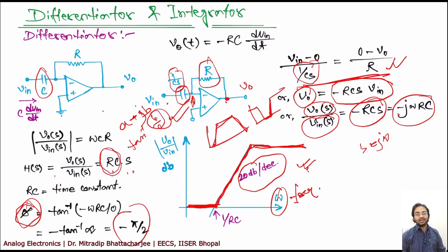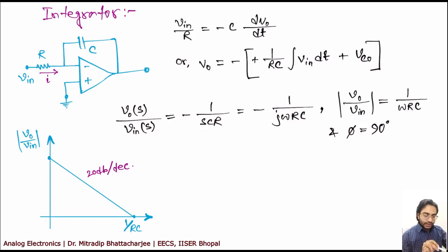So a filter is nothing but a concept that came from this type of circuits, from Bode plots, you can say transfer functions. Okay, so I am not going into details of the integrator. In the case of the integrator, you just put a capacitor in the place of the resistor and a resistor in the place of the capacitor. So you get this circuit which is the integrator.